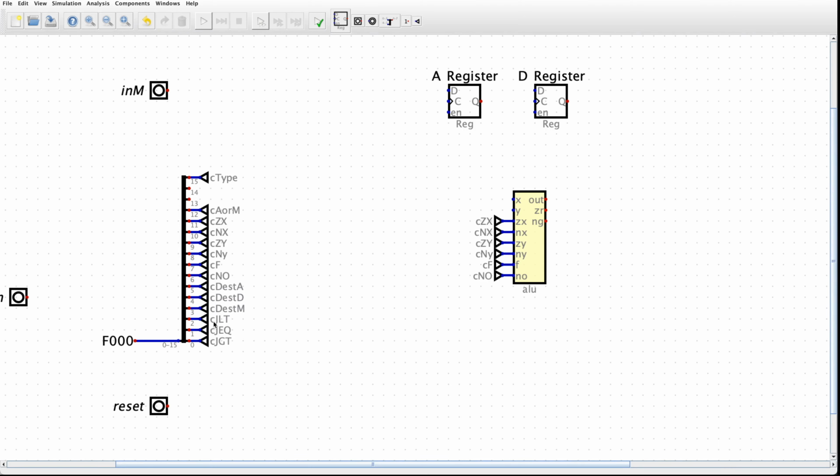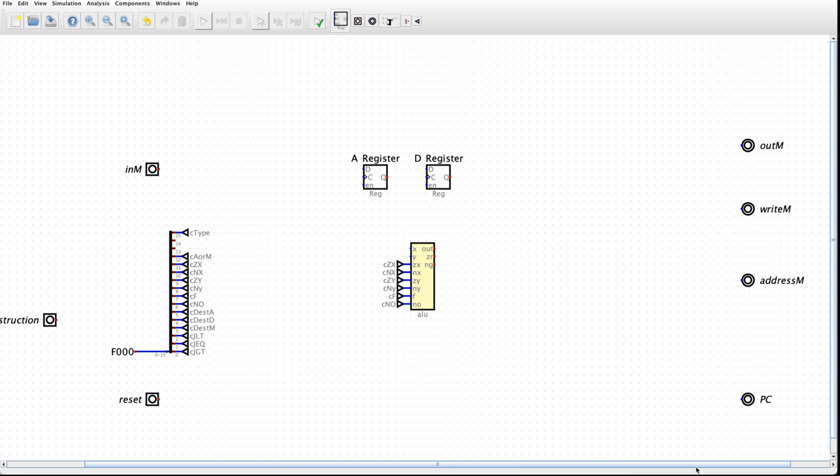So many of these are still not connected to anything useful, but they're at least primed and ready to go for us to put nets elsewhere and figure out where they're going to be wired up to. I'm actually missing a part that I need to graph this. I was thinking, let's do this reset button and wire it up to the program counter. That'll be easy. But I confused myself because this PC here is not a conduit to the program counter chip. This is actually just the 14-bit or 15-bit value that is the program counter.